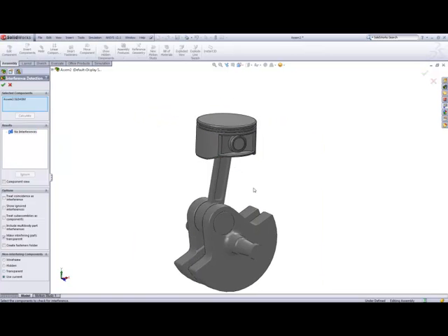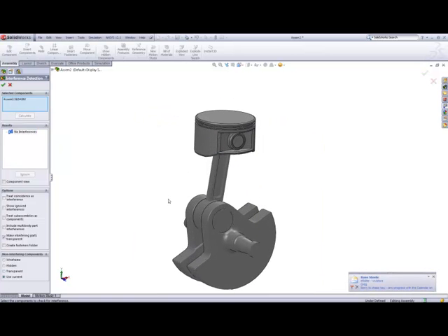And if we then do a tools interference detection again and click calculate, we'll notice now there's no interferences, there's no material overlapping. But what we might want to do is treat coincidence as interference. Now what that will do, any parts that are touching but not overlapping will show up as interference.